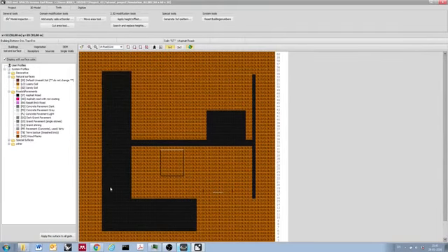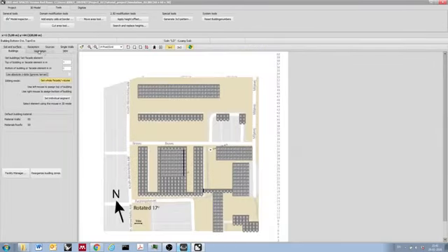Once all the soil profiles have been drawn, we'll find something like this. I use the loamy soil as the standard ground. However, you may use other types of soil, but this is the default one. At this point, we will start to check if our buildings are connected correctly and if everything is recognized.